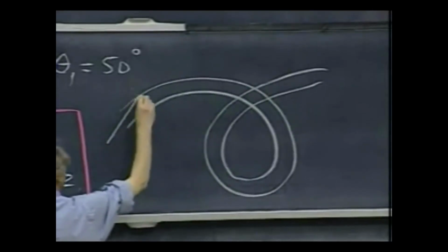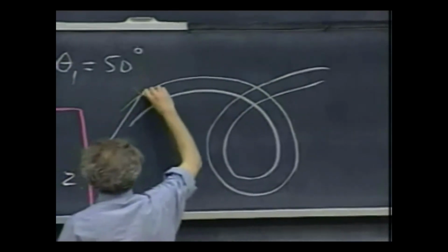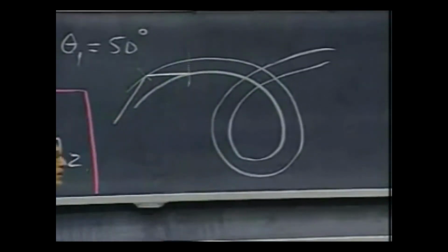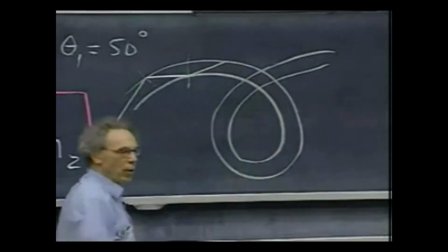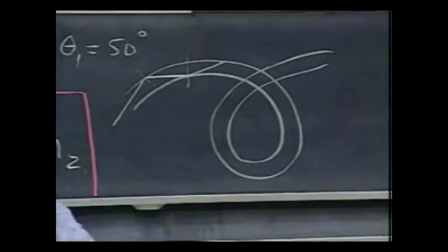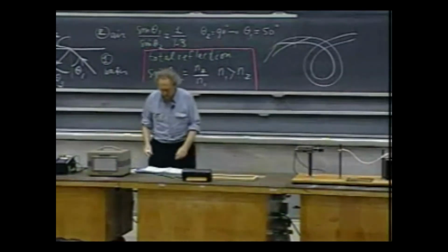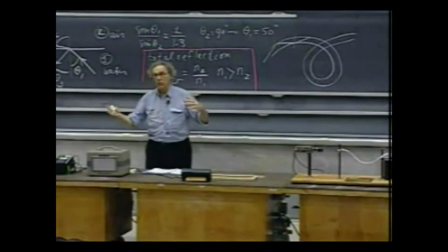If this angle of incidence is larger than the critical angle, 100% reflected. And so nothing comes out in the air, 100% reflected. Here, again, the critical angle is exceeded, and so 100% is reflected, and you can go through this whole thing for miles on end. You can put even knots in there. As long as you never exceed the critical angle, that light will propagate, and there will never be any loss of light. And that's why people are very much interested in it.